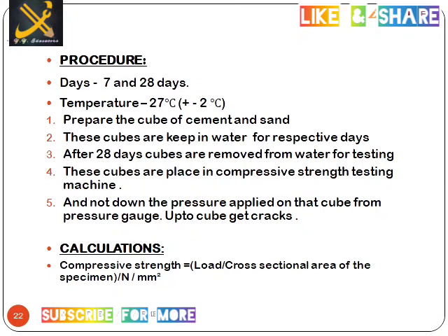This load can be calculated. The calculation of compressive strength will be load upon cross-sectional area of the cube or specimen. The compressive strength is in Newton per mm square.